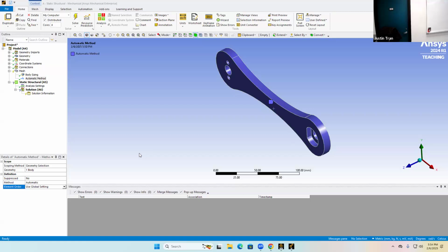Yeah, so that looks pretty decent already. So what I was telling him, we'll go over this in the future, but if you look in this direction, you'll see that there's two elements through the thing. That's usually a pretty good sign that you have a good relationship. Because if you remember from the default mesh, there's only one element here. So you usually want to choose the size small enough so you have multiple elements.